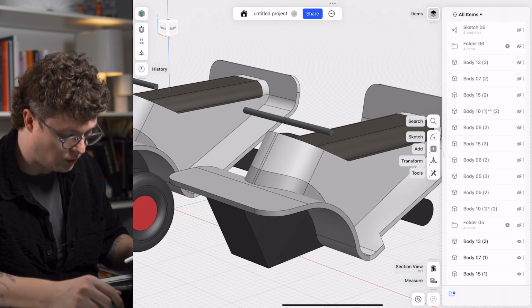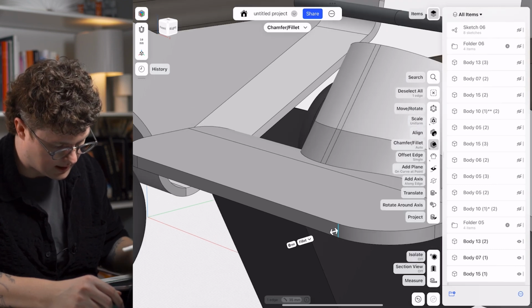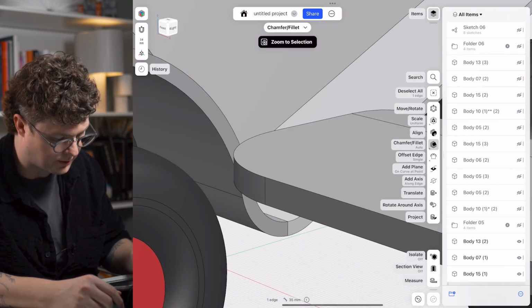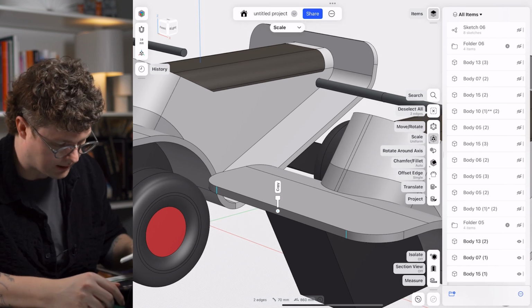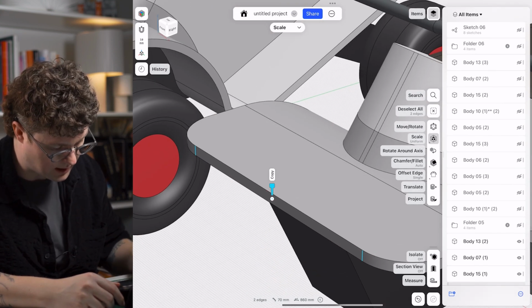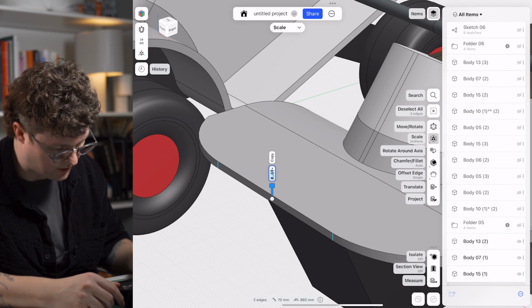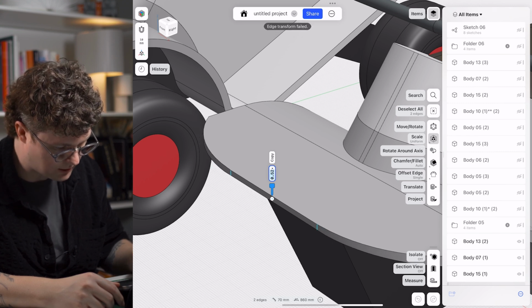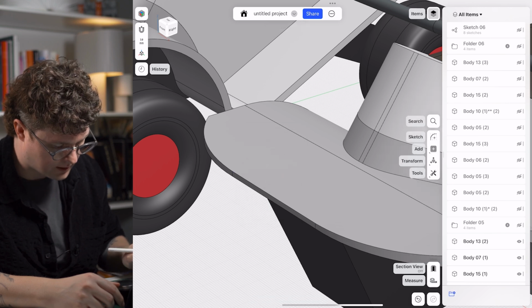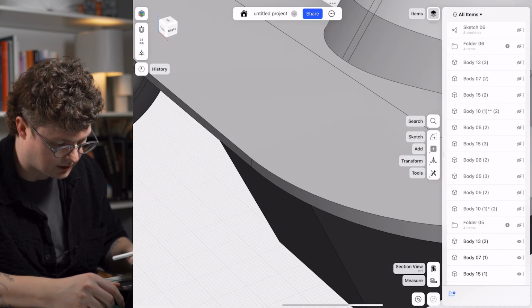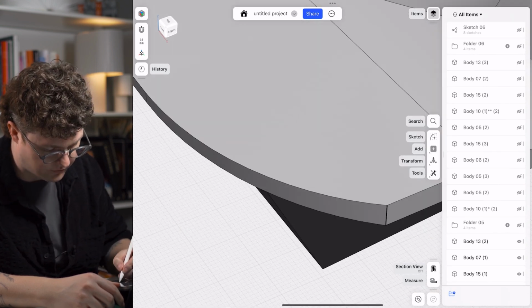And now that we have this really organic looking kickstand here, we could apply that to other sections if we want to, or we could come over and maybe we scale something. So let's say, let's select these front ones. We click on scale and then just very easily drag in. And you can see there that, let's say 0.5. Now that we've got this thinner section at the front, I can fillet this back off.